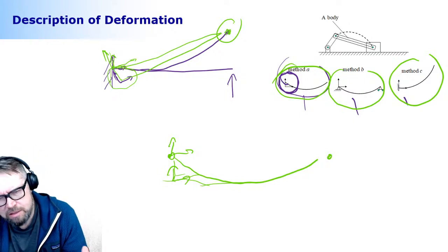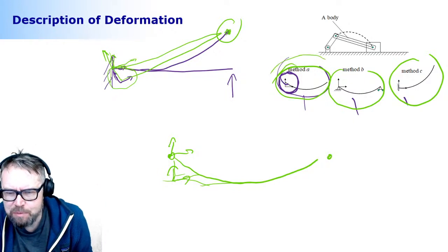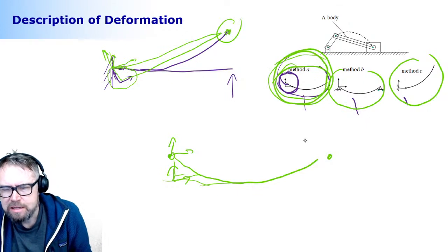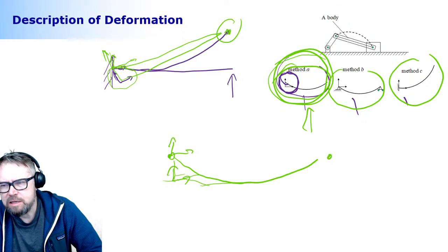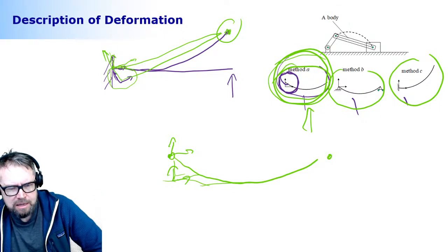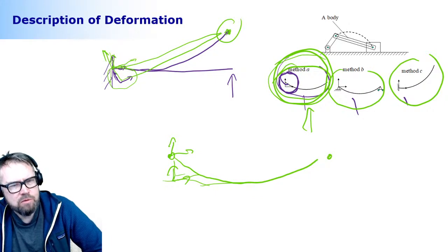To put it in short, this is where the possibility comes from that you can use no boundary condition at all. It's just the modes that are computed in a way that the structure floats in space. That's where the name, floating frame of reference formulation, comes from.